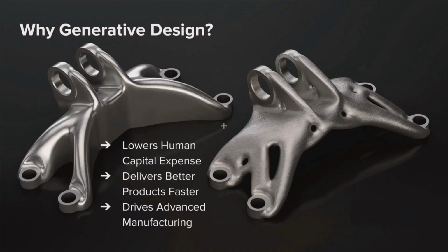So just for example here, these are two designs, one on the right and one on the left, that are both automatically created by our technology. The one on the right has 0 manufacturing constraints on it. It's essentially just free-form topology optimization, and the point here is that the designer only had to specify their user requirements and click generate, and that is what came out of the system. Same goes for the one on the left, but it has some extra constraints put on it, because maybe they wanted to reduce the amount of support structures needed or make it a milled part even. Yeah, we also don't ignore that we have other manufacturing techniques out there.